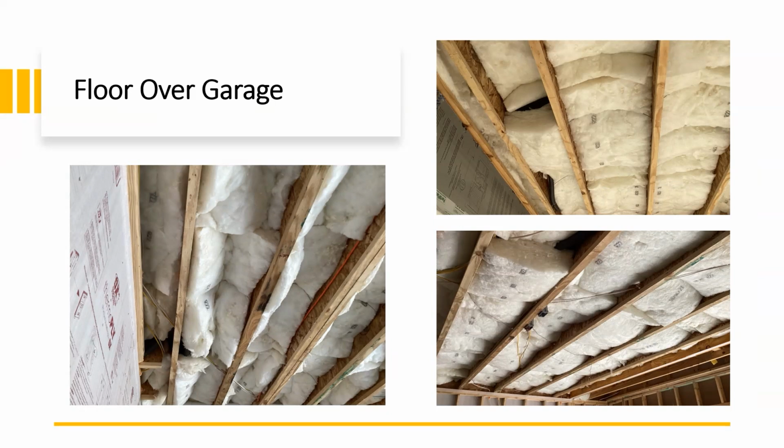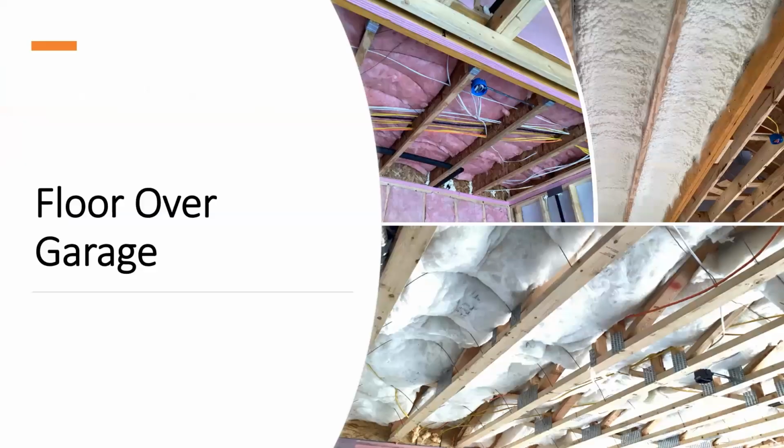And the one at the top, I also took that one as well. I took a stick in the ground and just poked up one of those bats, the one closest to us on the left. When I pushed it, it went all the way up and left a massive gap, which told me that's not properly installed. So it should be corrected. Here we just see three that were correctly installed. The top left is traditional TJIs, the top right is open cell foam, and the bottom is through the truss system. So those are all being done correctly.